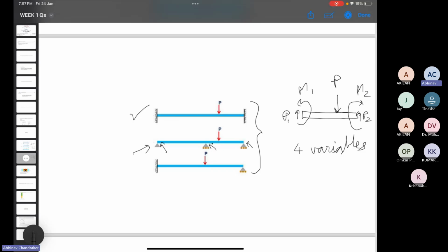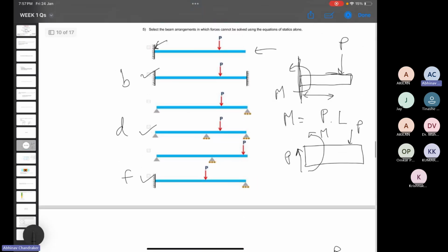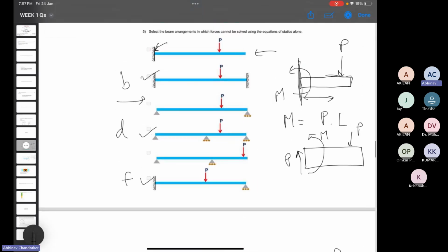So if you want to do a force balance, you will have three variables in this one equation. So here also you cannot tell what will be the value. You will also have a moment equation. So you will have two equations, but three variables. While in this case, you only have two contact points, right? For the C case, for these two contact points, you will have some forces and you have two equations and two variables, so you can solve it.